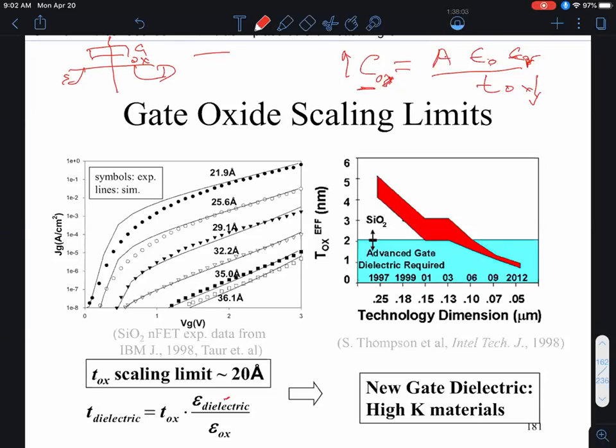Okay. Now this oxide provides a large energy band gap. The gate doesn't have a band gap. It has the work function in the metal, and the semiconductor channel has a lower band gap. So hopefully carriers can flow across this barrier because this insulator is a very large band gap material. But of course, we studied in chapter 2 that as you make this barrier thinner and thinner, carriers don't necessarily have to go over the barrier, but they can simply tunnel through the barrier. And the tunneling current we've seen depends not only on the height of the barrier, but also the thickness of the barrier.